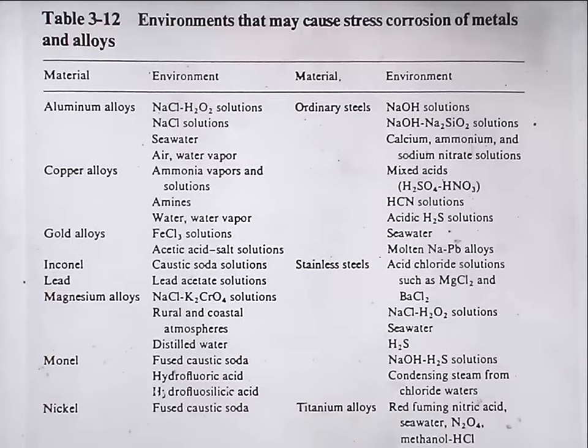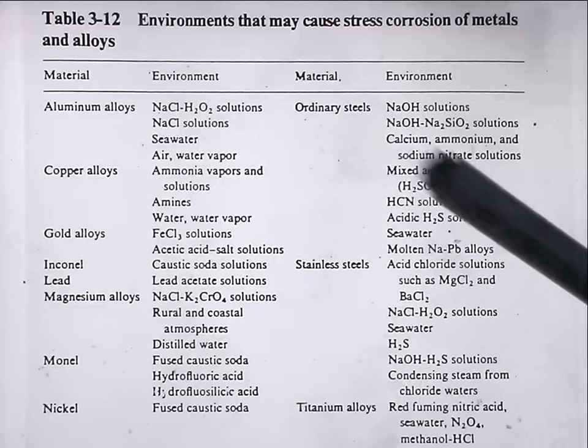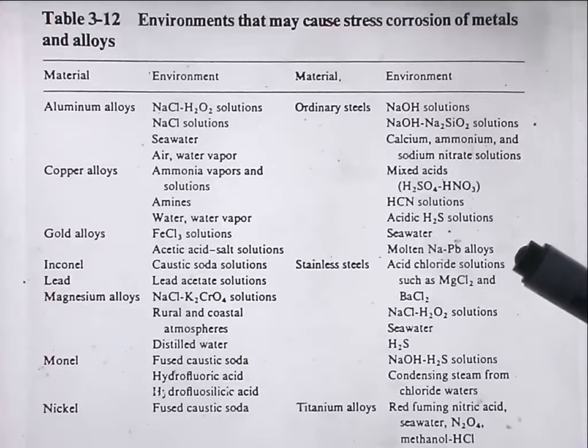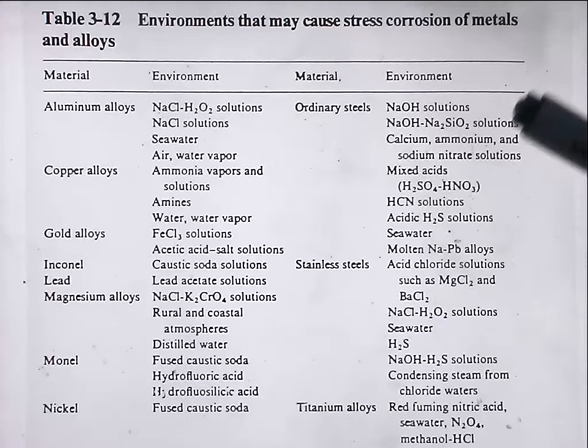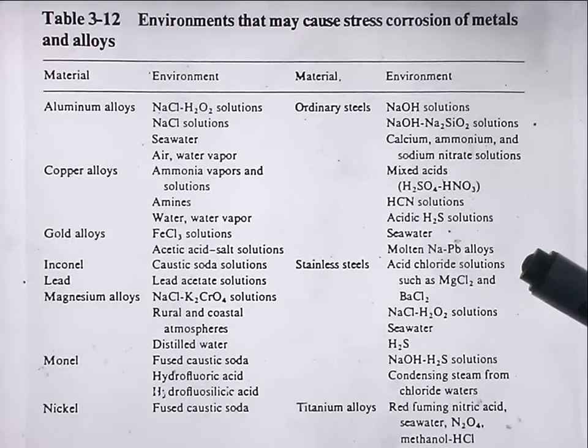So we get a lot of cracking in Inconel alloys, in power generation systems. We get a lot of cracking in steels in a whole range of environments. And so it's really much more common. And the failures you get, you've got to inspect vigorously for, because the superficial appearance of your component is that it's all right, but it's actually got a hairline crack in it, and it's waiting to fail.